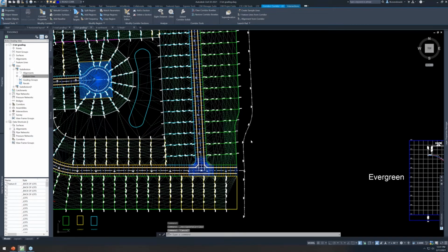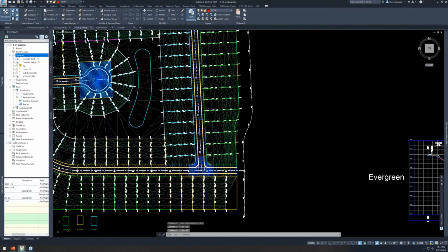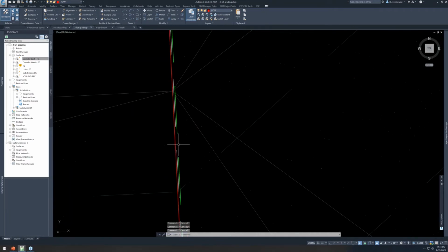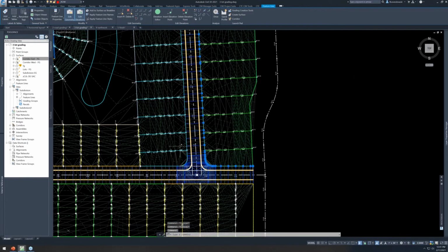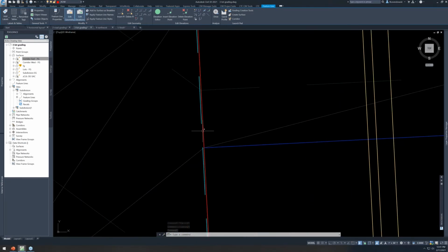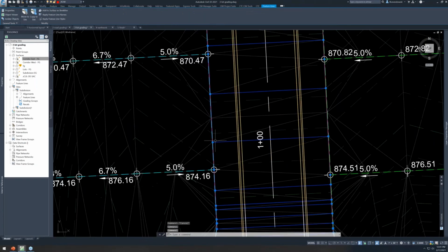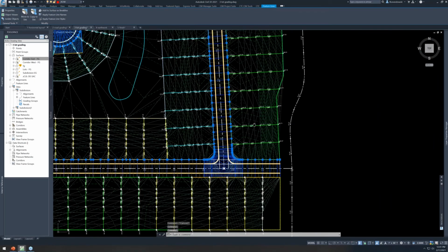Okay, that rebuilds. And this is the corridor east surface. So next thing I want to do is grab those feature lines. I'm just going to grab the two that are right here. These are my right-of-way lines. Remember, these are basically my baselines for my lot grading.